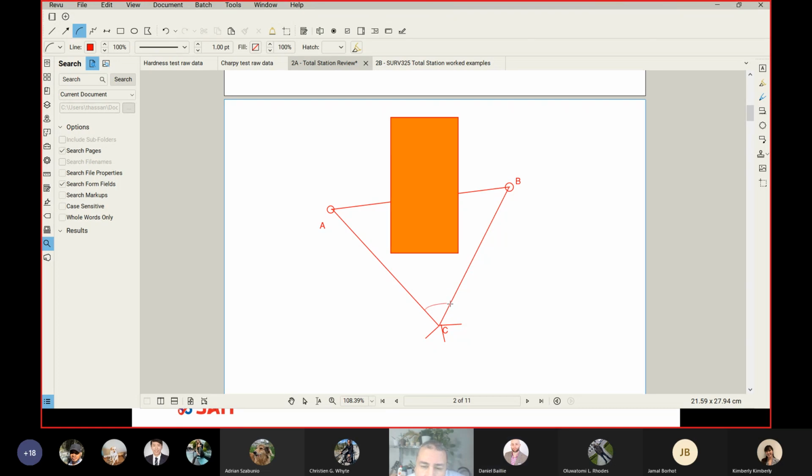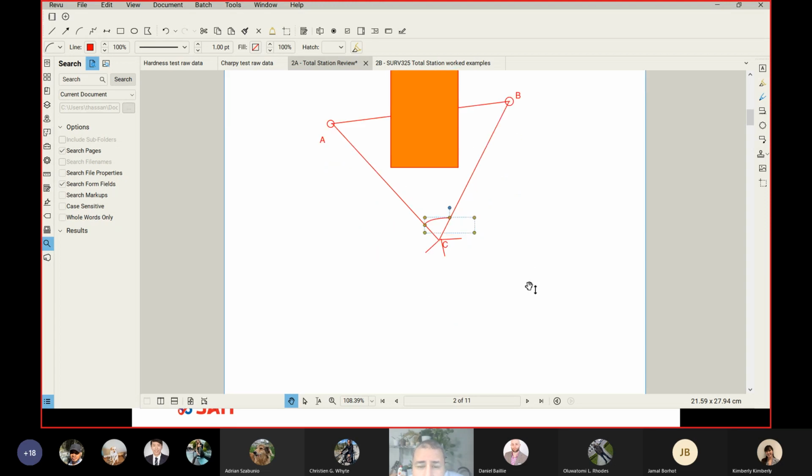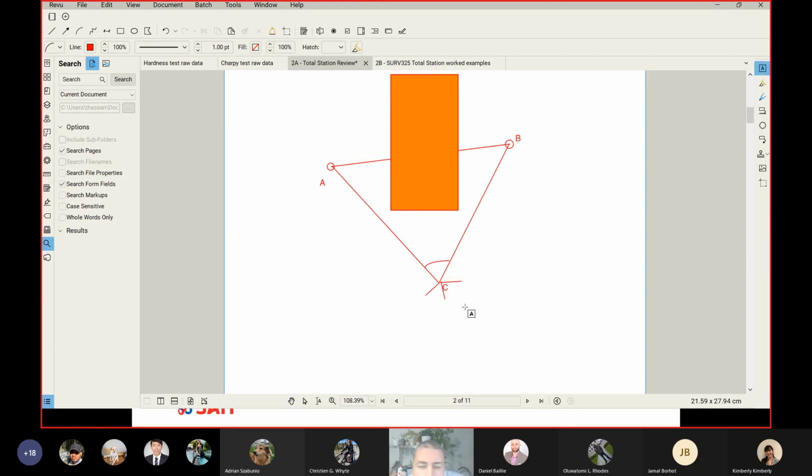So that's really what I'm missing here, which is the angle between A, C and B, which we can get using the total station. Take a reading, and get the difference in readings, and I'll get the angle. Then finally, what do I do if I have all these measurements? Watch me, please. Here I'm going to do it. You guys know something called the cosine rule.